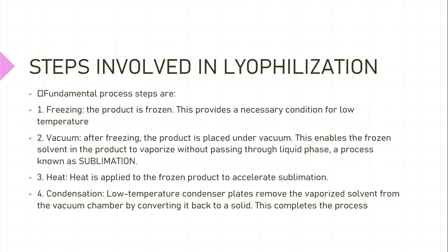The fundamental process steps involved in lyophilization are: number one, freezing. The product is frozen. This provides the necessary condition for low temperature, of course. After freezing, the product is placed under vacuum.